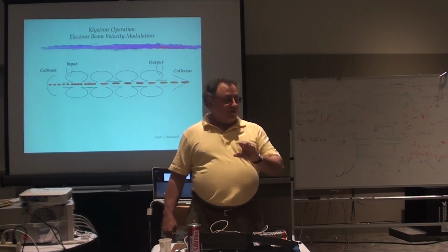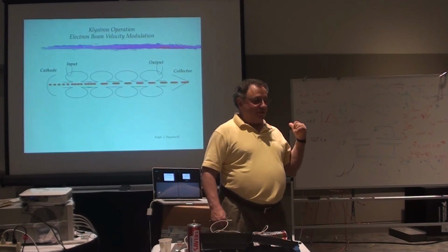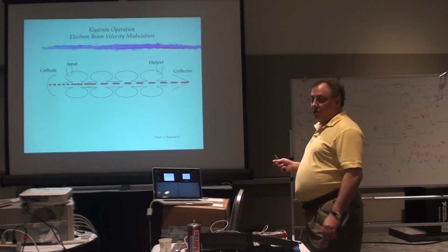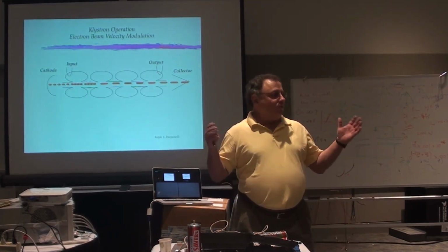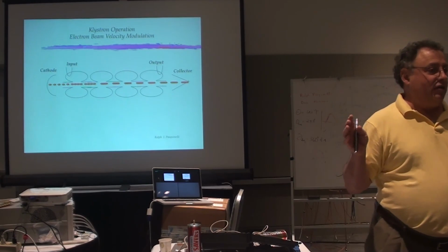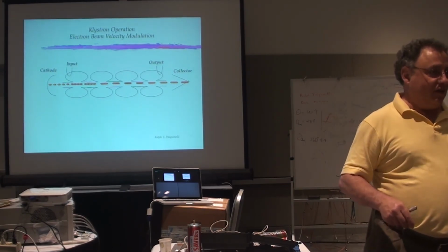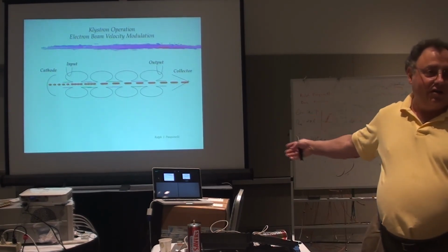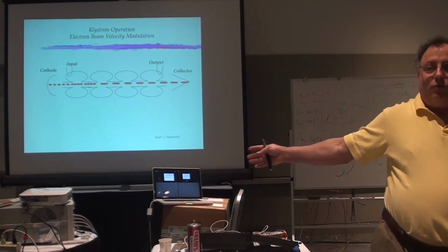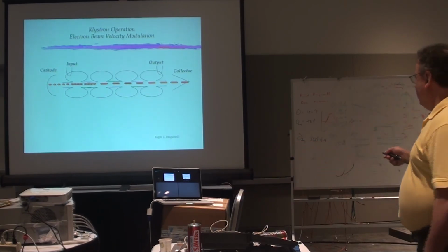If I don't have a circulator, it goes right back to the amplifier. Can the amplifier take a reflected power over here more than the spent electron beam? Hopefully it can, because a klystron, when there's no RF applied to it, is 0% efficient. The beam keeps on crashing right into the collector regardless. So that's not what's going to kill it. What's going to kill it is someplace over here.